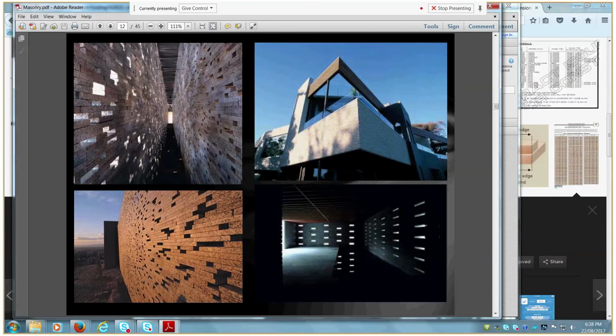In the situation with clay bricks with mortar, your mortar will shrink slightly, but your clay bricks will take up some of that moisture and they'll expand slightly. So much of your expansion and contraction is equalised in a clay brick wall, but in a cement or concrete block wall, if those concrete blocks aren't adequately cured, you can have significant contraction over a wall.